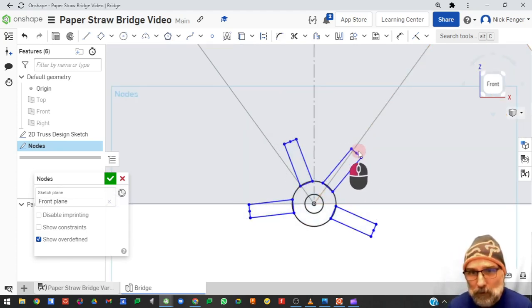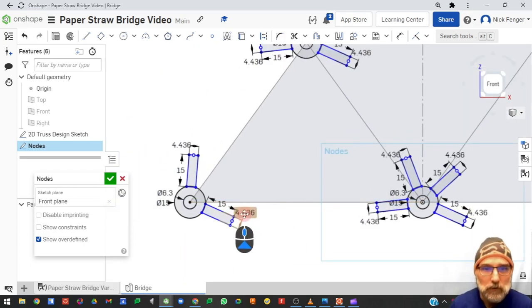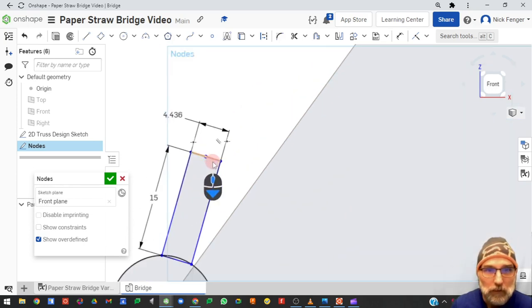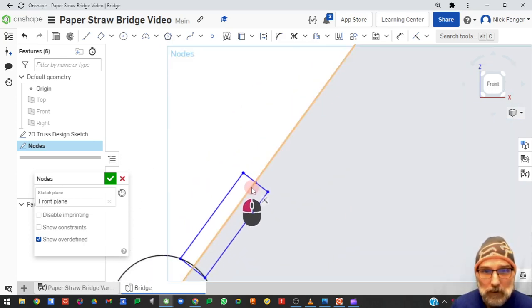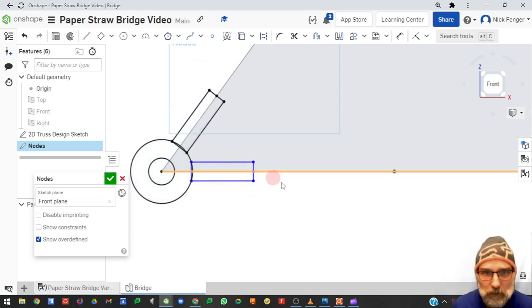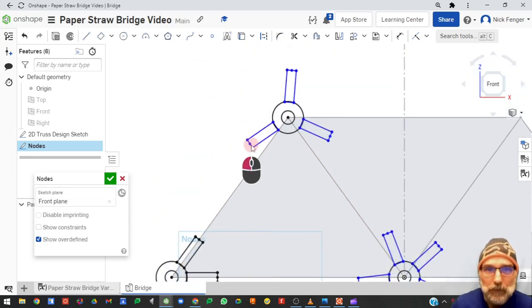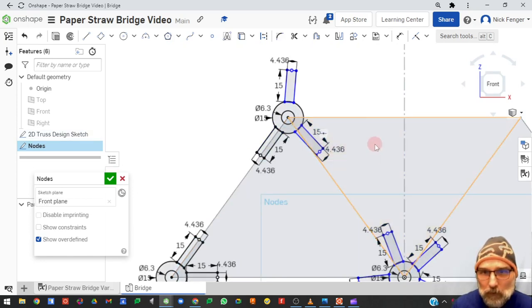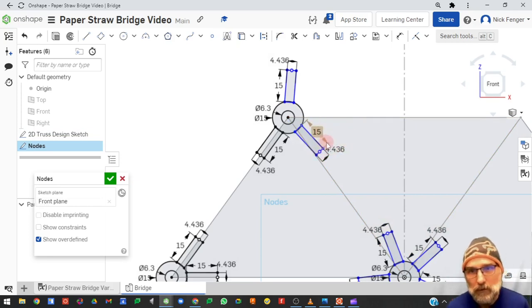Now, it got kind of close, but so now let's go back to our original node, and let's constrain it to the original sketch. So this should give us, notice, one constraint. We're grabbing onto this point and dragging it onto here, and that's going to constrain it. You see the coincident show up. I'm dragging it. Boom, it turns black. Same thing here. Drag and do a coincident, turns black. So keep doing that and get them all aligned. Just move it until you get the coincident showing up. Oop. If you get too many things selected, just hit spacebar. Boom.